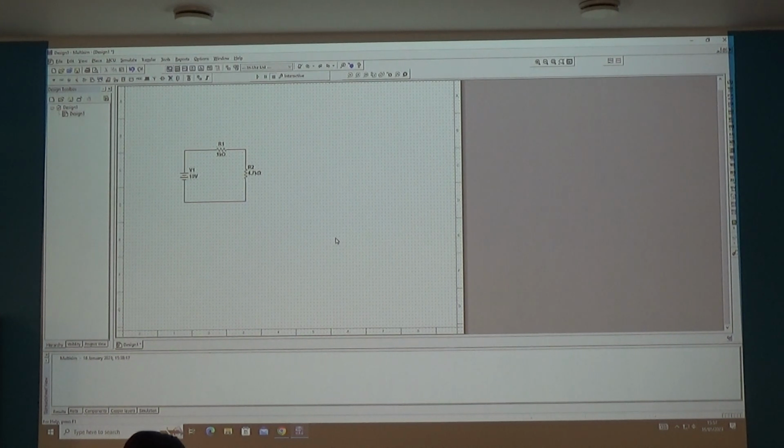So that circuit you've got there is what's called a potential divider, and actually I think the vast majority of all those circuits descend down into something that's that simple. You know, what's the magic, what's the miracle of electronics? That is. Okay, well this could be a capacitor here, actually, this could be an inductor, but that's no difference, the maths is the same. That's a potential divider.